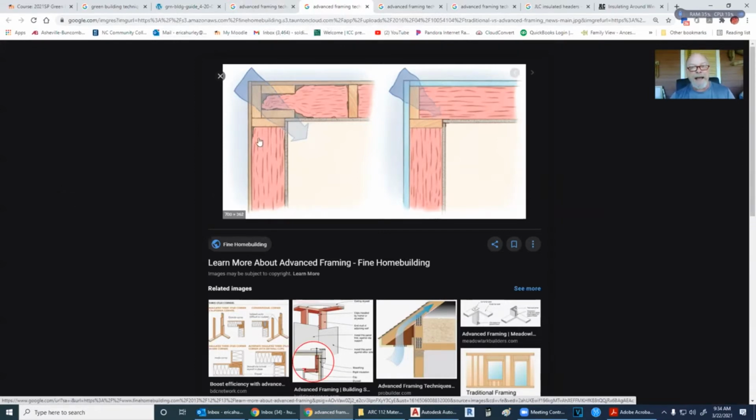So as you can see, the insulation gets squeezed into places in the corner where we have a lot of studs. Now, one of the biggest problems that I see in insulation is they will take insulation that is made for, in this case, 5.5 inches. These are 2x6s, and they just compact it down in here. Especially with fiberglass insulation, when you squeeze it into a smaller section, you're in a sense getting back to a solid piece of glass. A solid piece of glass is a conductor of heat.